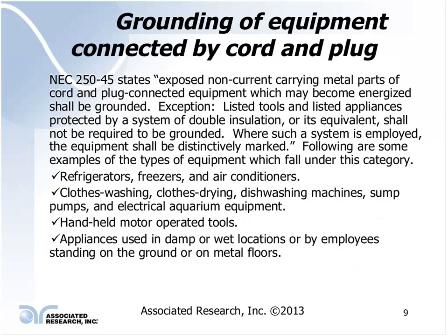Okay. What does the National Electrical Code state? NEC 250-45 states that any exposed non-current carrying metal parts of cord and plug connected equipment which may become energized shall be grounded. There is an exception to this.